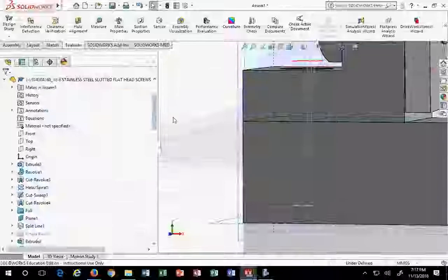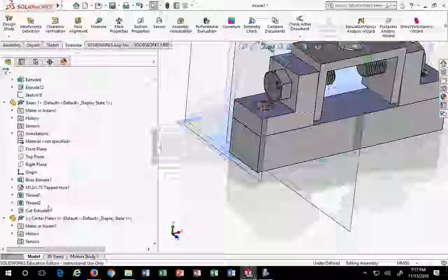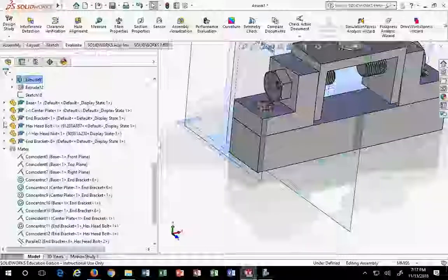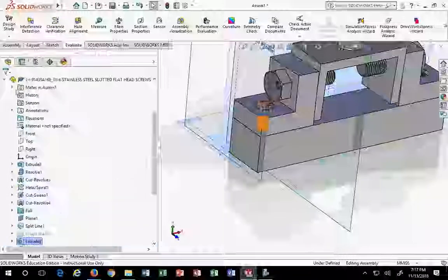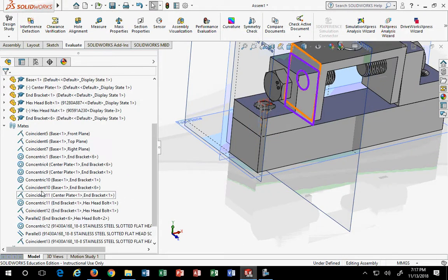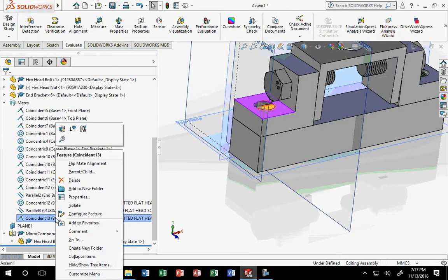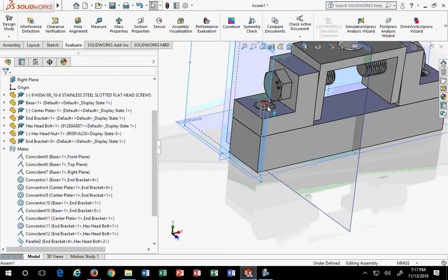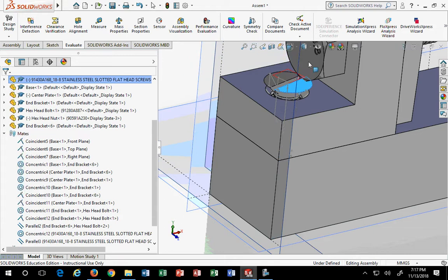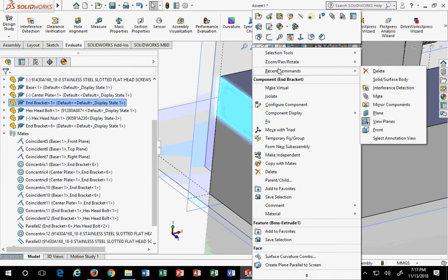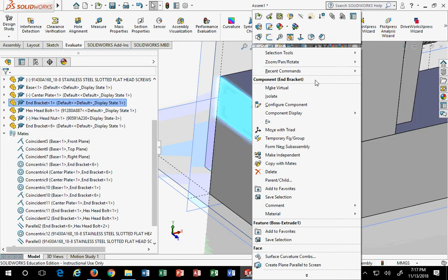So with that in mind, you realize what you have to change. It's a straightforward fix. You've got to change that L bracket to accommodate the fastener if you want the fastener to be flush. So if I delete that constraint, that mate, and pull this part out, I can go ahead and actually open this part and fix it.